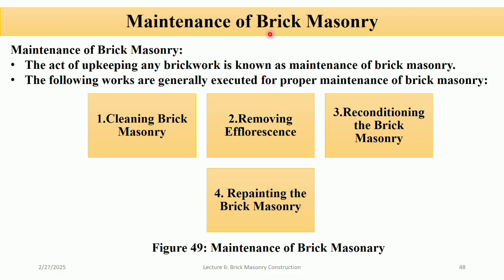Now let's discuss maintenance of the brickwork. So the act of upkeeping any brickwork is known as maintenance of the brickwork. So the following works are generally executed for proper maintenance of the brickwork. Number one is cleaning brickwork. So the dust and growth of organic matter, if any, is to be removed occasionally to ensure the neat appearance of brickwork.